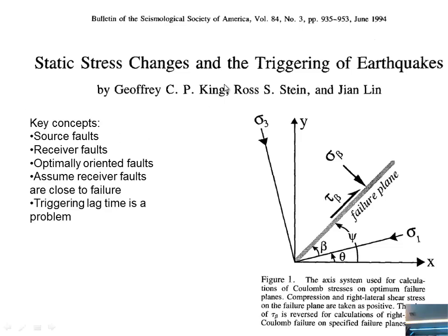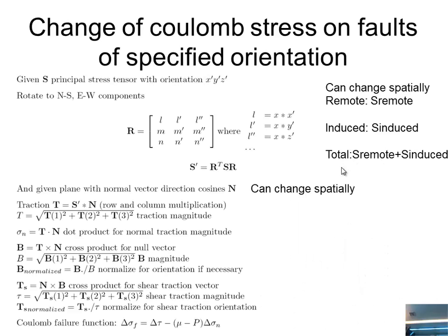And so you have basically the idea of some remote stresses. You have the failure planes. You have to take these remote stresses and resolve them into the shear and normal components of stress on the plane. This is basically the vector calculus that does it, and this is what's programmed. If we had a week, we could do this ourselves in MATLAB.